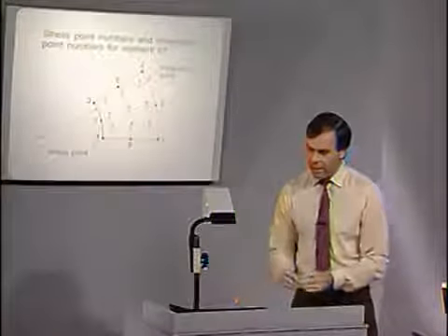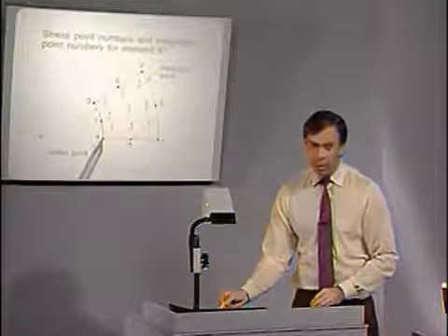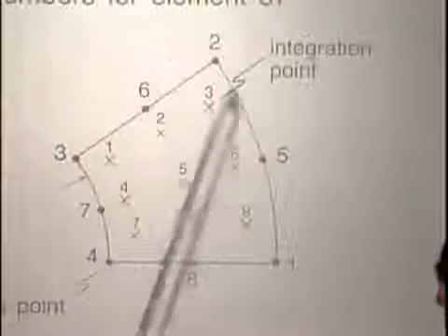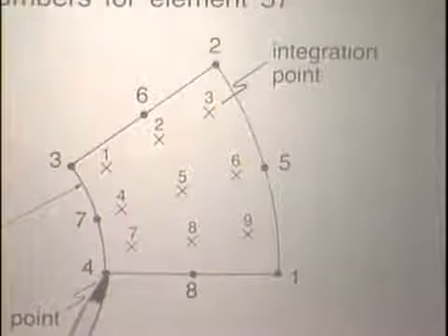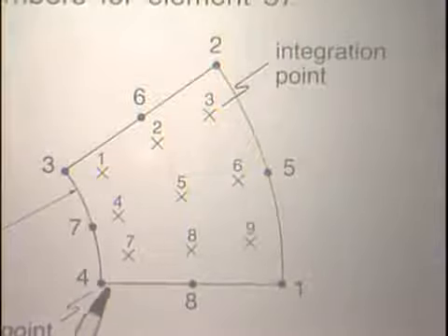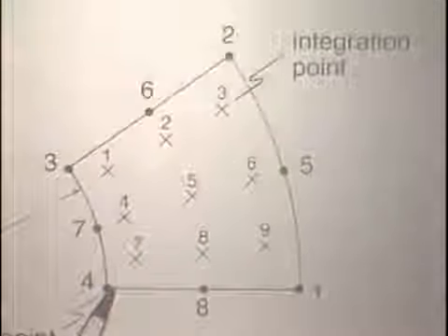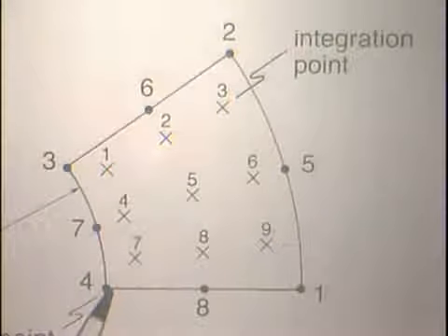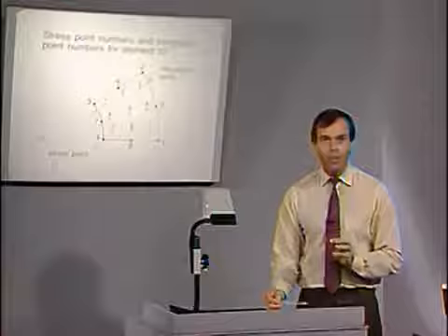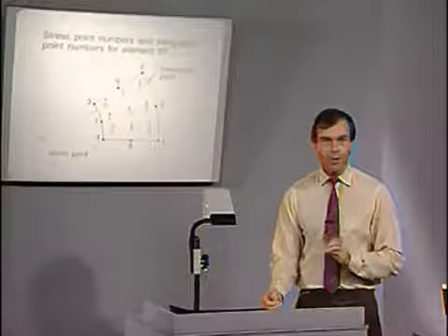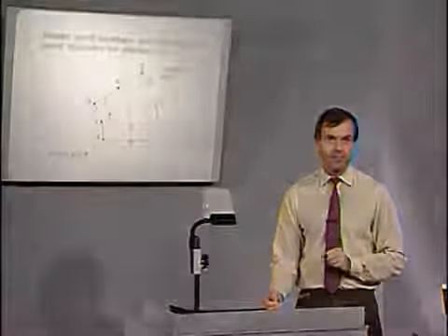We will see that doing so, ADINA-PLOT tells us that this is the point, element number 57, point number 4, that is this physical point here, where the maximum stress occurs, and it will also give us that maximum stress. And that maximum stress, of course, gives us then the stress concentration factor. So let us now look at this phase of the analysis.